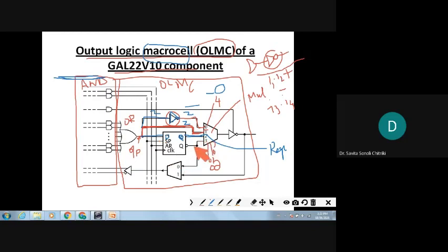And at point number 3, you see there, through the multiplexer, it is fed back. So if this tri-state buffer is not active, that means directly whatever the output is there, that is being connected here. So here the input is fed back either like this or directly through the pin. So this is a 2 to 1 multiplexer here. For a 2 to 1 multiplexer, how many select lines do you need? Only one select line is needed.